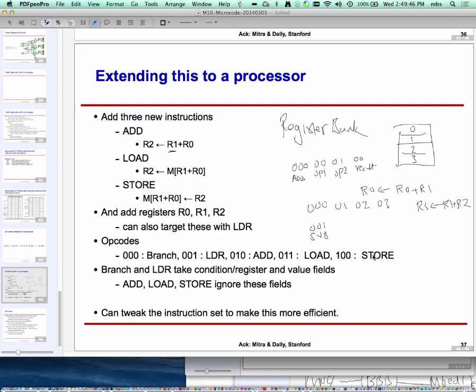So you're saying like these branch instructions, is it like in order to make the address memory thing, you load software onto the hardware in order to create these instructions? There are two ways of doing it. This microprogram memory, microcode memory, may be a writable memory. So when you write your program, you burn it into it. Nowadays, typically, it could be flash memory. The advantage is I power it off, the program is still there. On the other hand, if it is a RAM, then every time you power off, replace battery, you have to rewrite it. So that's the second approach.